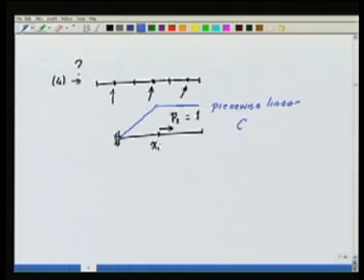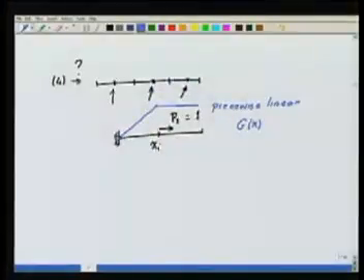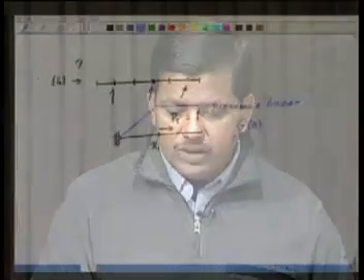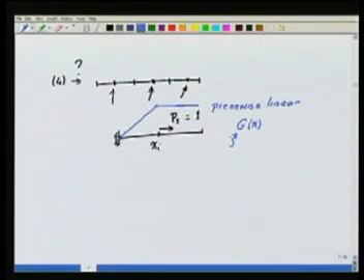Let's call this solution G, G of x. So this solution is piecewise linear. Now my question is, as we had discussed earlier, by putting a node here, by having a mesh, should I be able to represent this exactly using my finite element solution or not? Answer is yes. So this will be equal to the finite element solution.